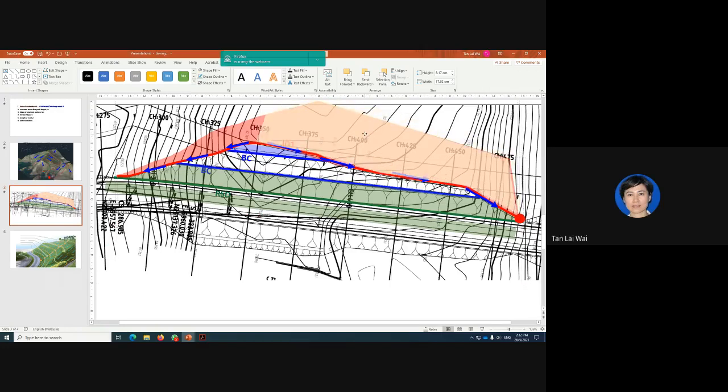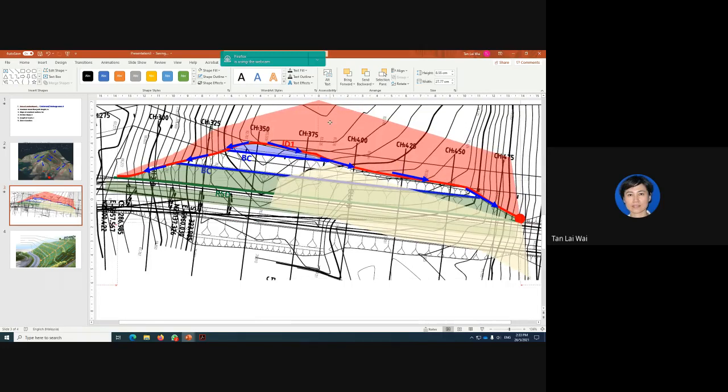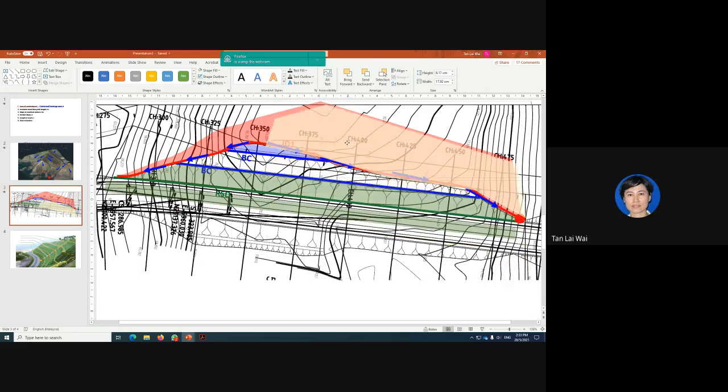Now, if you look at this, I draw another catchment area. That's why in my video I explained that you need to determine the direction of flow in the drainage first. Why? If you consider the whole interceptor drain, this would be your catchment area. However, if you consider the direction of flow in the drain, it splits into two parts going to the left and right. So that